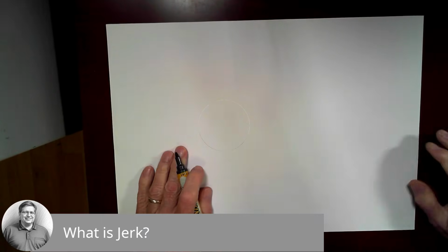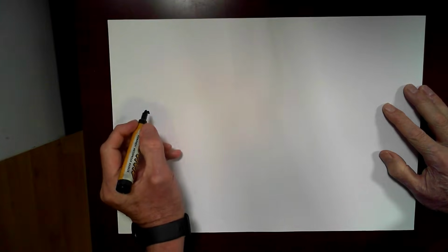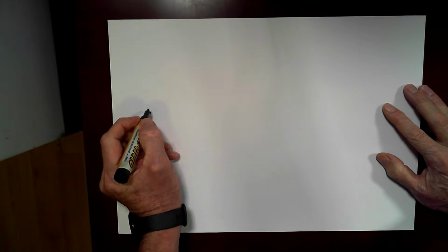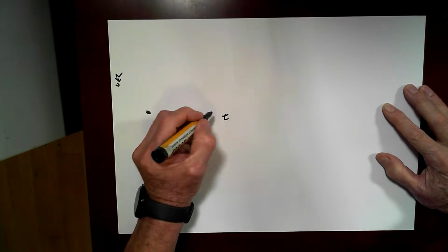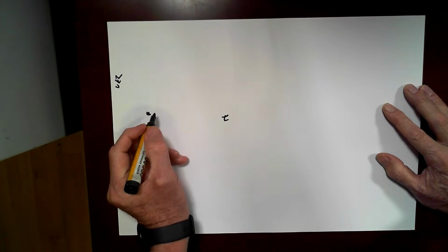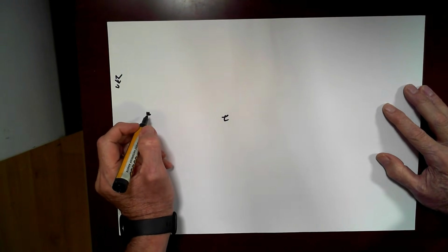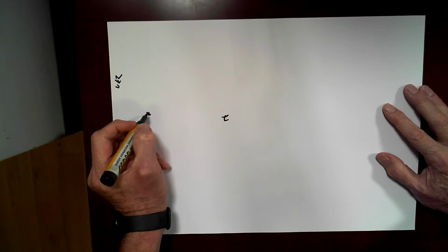So let's have a look on a piece of paper at what a motion profile looks like. Normally, what happens in LinuxCNC, you've defined your max acceleration and you've got a start point here, let's just say it's 0, and you want to get to, if this is speed, velocity, and this is time, what we want to do is, say we're accelerating to a cut speed of, say, 2 meters per minute.